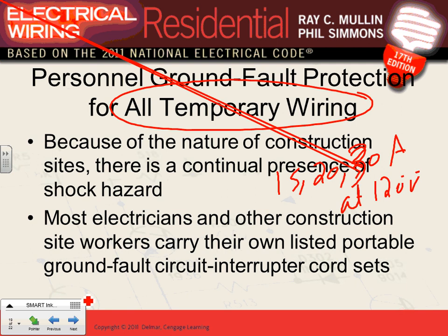This applies, guys, to a compressor. You have a 240, 30 amp compressor on the site, right? So yours is not GFCI, but it has to be on a ground fault program. They call it the assured equipment grounding conductor program, meaning you have to test that the equipment grounding conductor is working, it's not frayed, and all this good stuff. Any question, guys, about the construction? So construction, 15, 20, they add 30 though. 120 have to be GFCI.